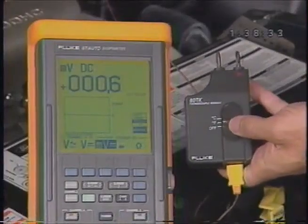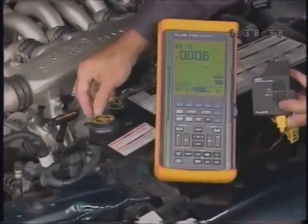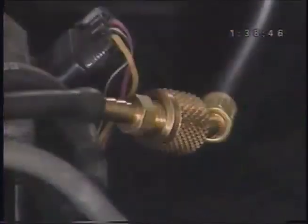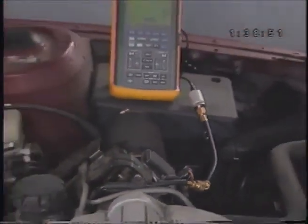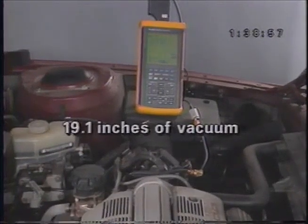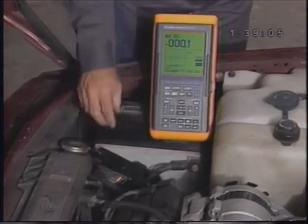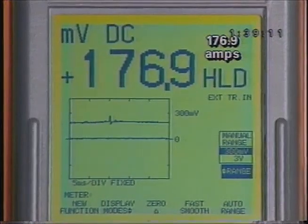A temperature transducer lets you use Scopemeter as a digital pyrometer, providing instant temperature readouts of cooling systems, exhaust systems, even air conditioning system temperatures. A pressure transducer allows Scopemeter to double as a vacuum pressure gauge. Read precise vacuum or pressure levels for testing engine vacuum, fuel pressures, oil pressures, even tire pressures with electronic accuracy. An AC-DC current clamp lets you use Scopemeter to measure precise current draw from solenoids, relay starters. Even check charging system output with your Scopemeter.